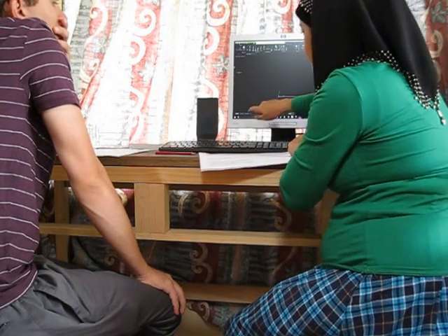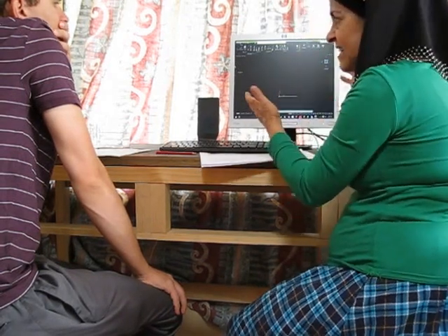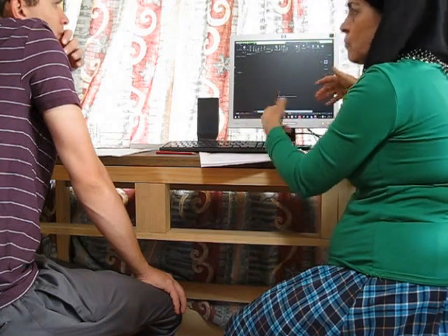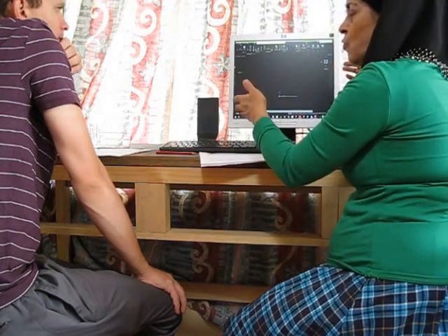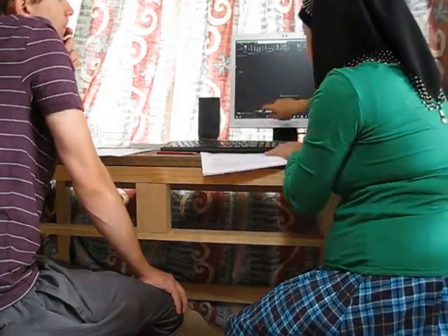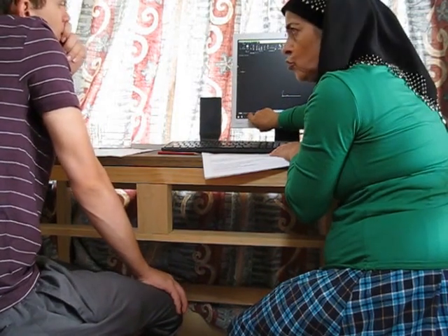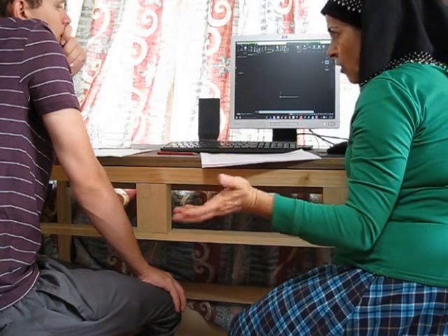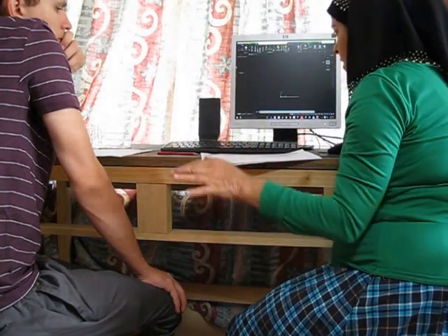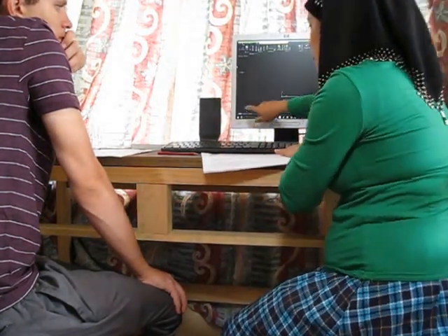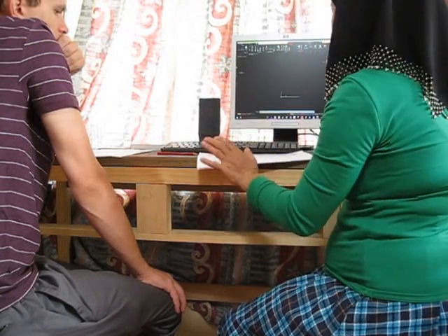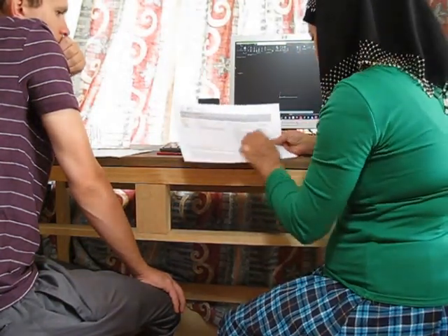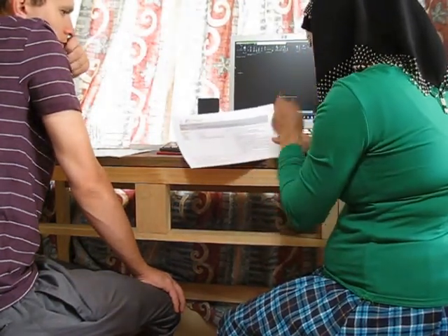If you want different scales of this drawing, 5 times more, 10 times more, 100 times smaller, then you use layout 1 and layout 2 to create different printings with different scaling. So at this level 1, we just use the model view. We don't want to care about layout 1 and layout 2. Make it simple.